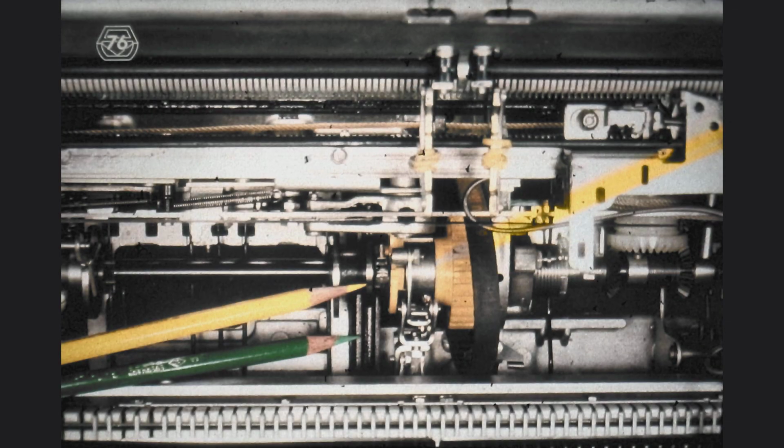From above the machine, we can observe the -5 rotate cam and the R5 rotate cam follower, also called the -5 rotate bail. It is important to notice that at rest, the cam indicated by the yellow pencil is positioned so that it pushes down on the cam follower indicated by the green pencil. This tells us that at rest the cam follower has used all the motion it can get from the cam indicated by the yellow pencil, and that if it is to operate during a cycle that requires this mechanism, a spring must exist somewhere capable of causing the R5 bail to follow the cam.